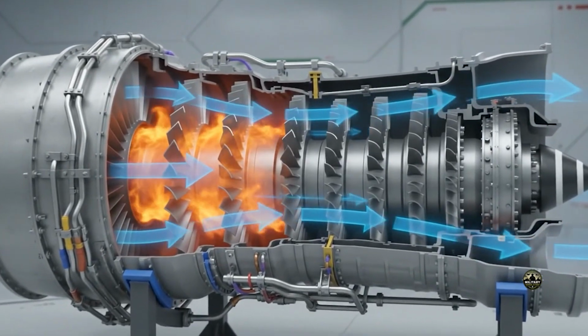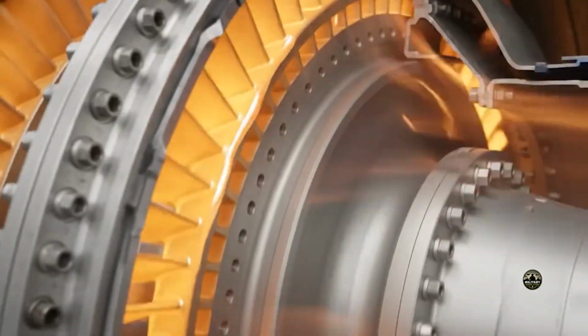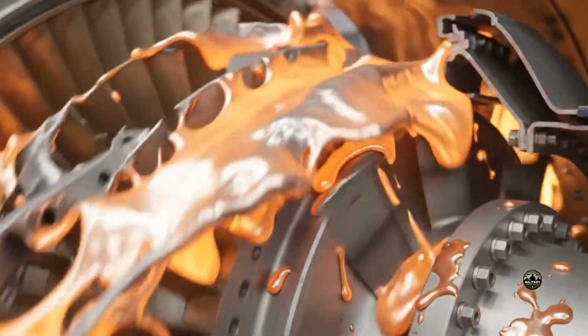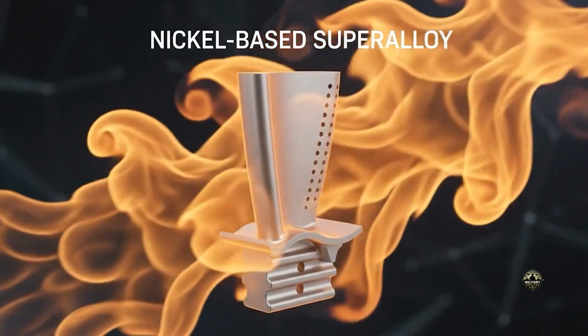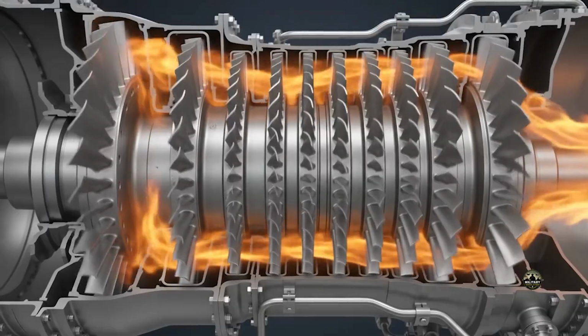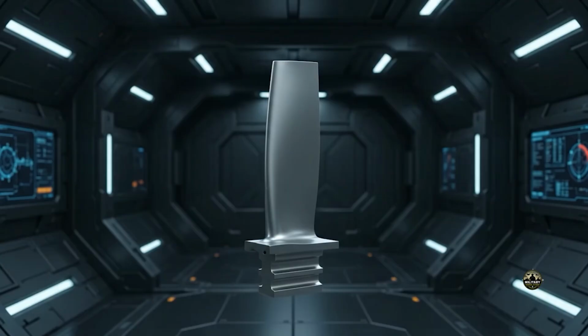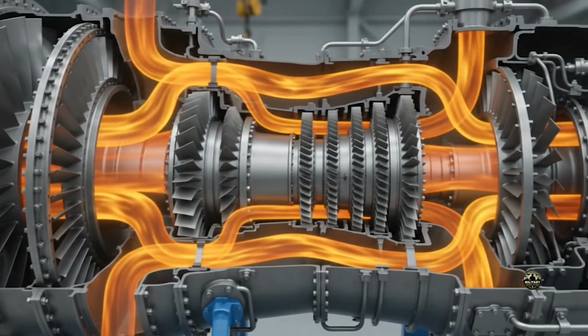The gases entering the turbine can be hotter than the temperature at which ordinary metals would melt. So why don't the blades melt? Turbine blades are made from advanced nickel-based superalloys, engineered to maintain strength and resist deformation even at extremely high temperatures. Turbine alloys contain carefully selected elements such as chromium, cobalt, aluminium, and titanium. These improve strength, oxidation resistance, and high-temperature performance.